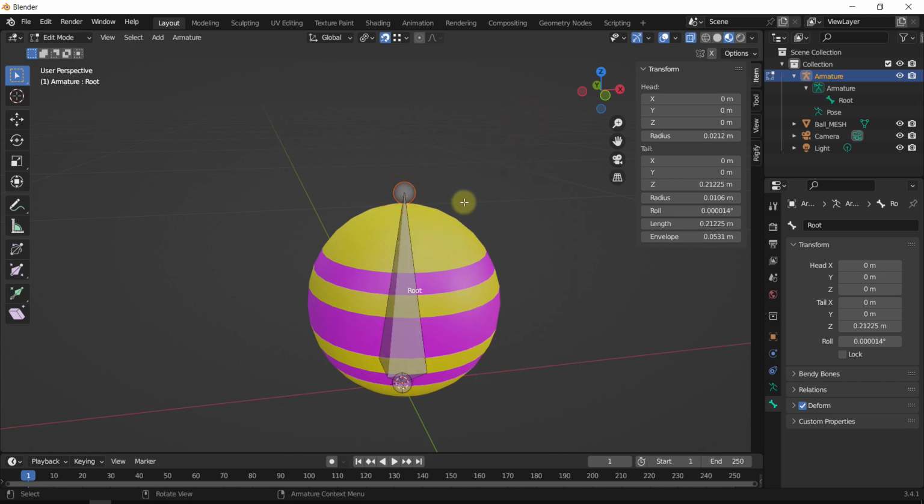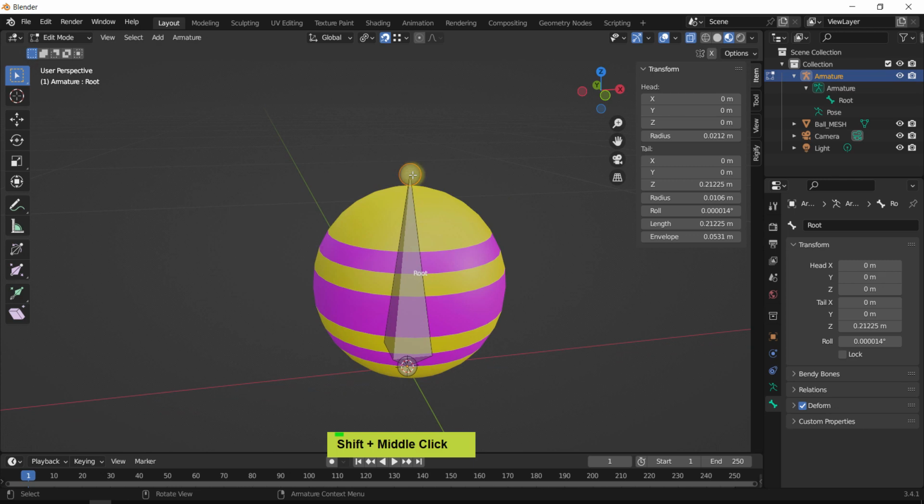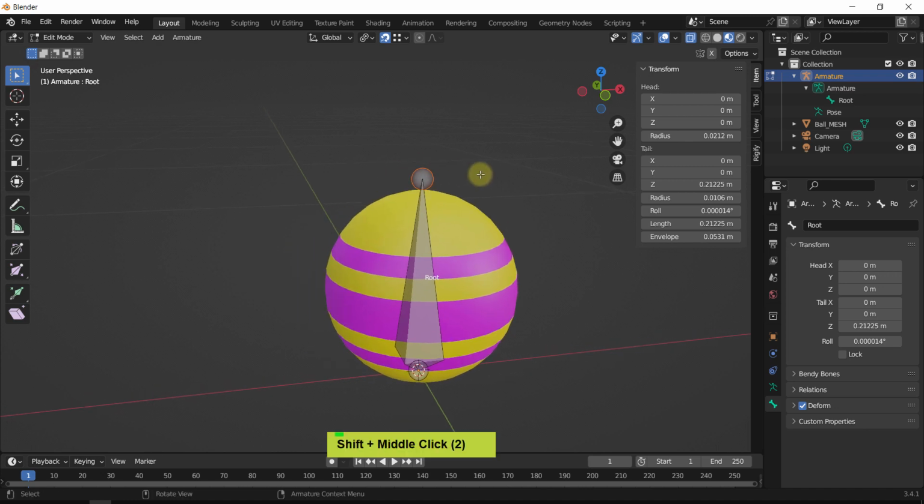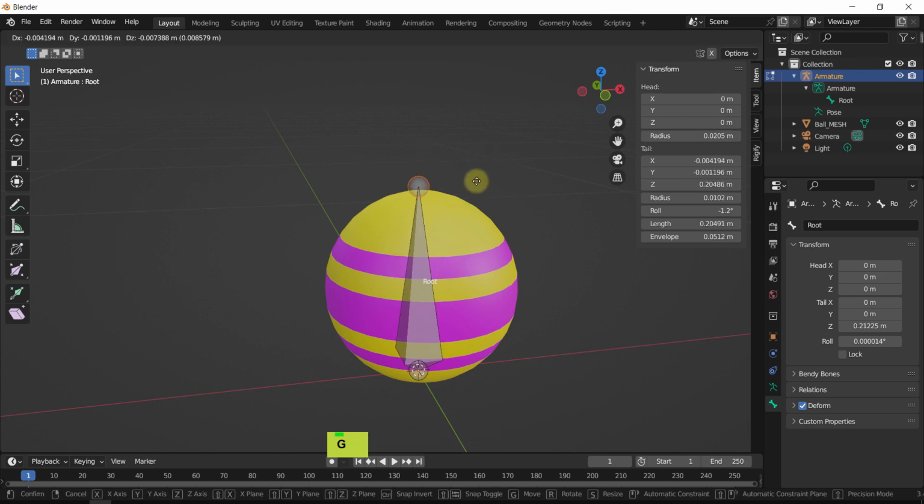Now the reason we did this, we are still in edit mode. We are selecting the end tip of the bone. Okay, I'm coming from out of software, so this is why I will call it a tip, but in Blender it's called in different ways. So there's the root of the bone, and here's the link of the bone, and here's the tip of the bone, the end of the bone. And that end could be positioned individually. So if I'm pressing G, it will just move away.